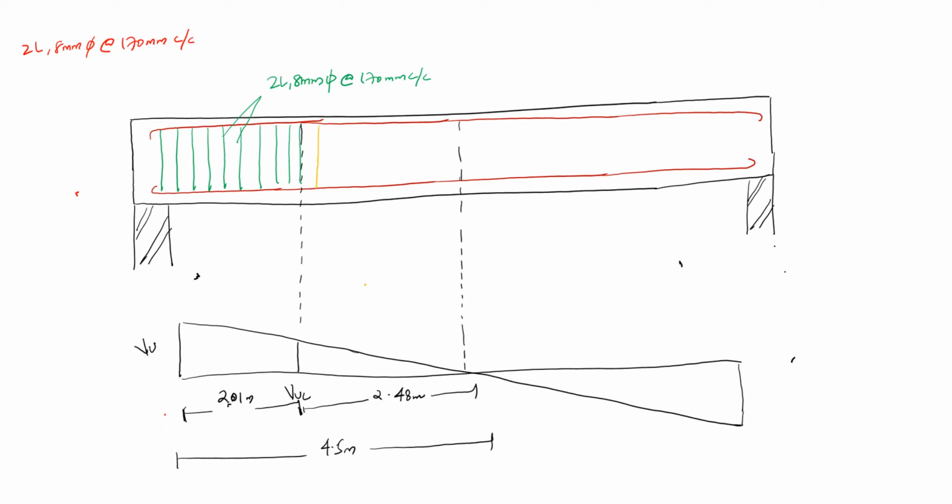I'll provide this 2-legged 8 mm at 225 mm center to center. So similarly, you need to draw it for the other side also. So I hope you are clear with this design for shear.